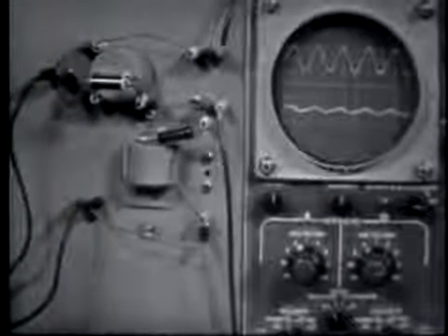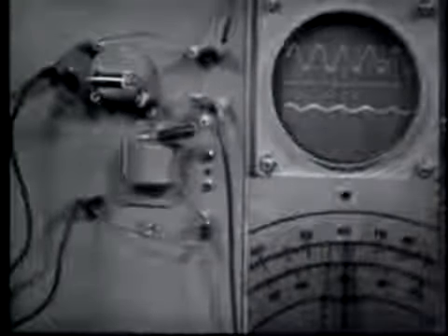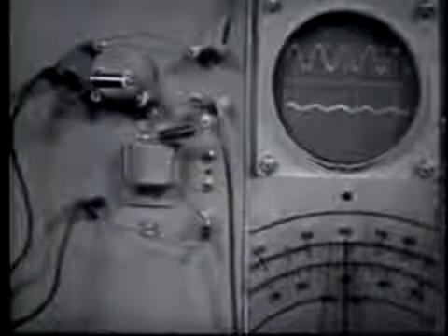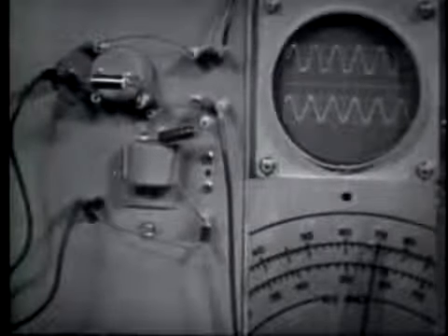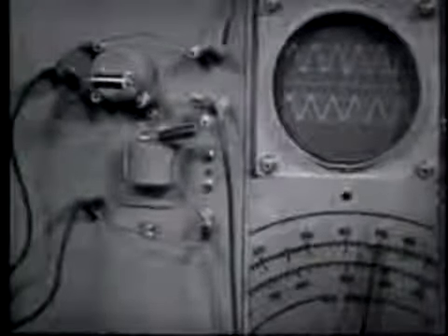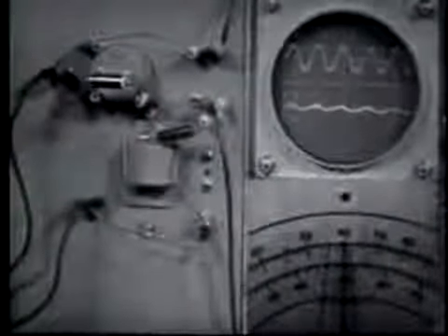Now we've said that the T and pi section filters provide improved filtering action over the simple L section. What do we mean by improved filtering action? Just this. This L section band reject filter rejects a band of frequencies from about 500 hertz up to about 700 hertz. Now since the specific frequency we want to reject is 600 hertz, this circuit is not too precise, is it? So let's make a T section from this basic L section and see if we can improve the frequency response.